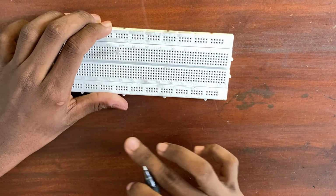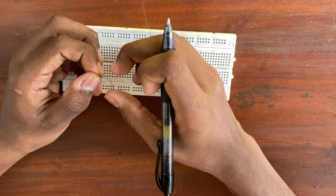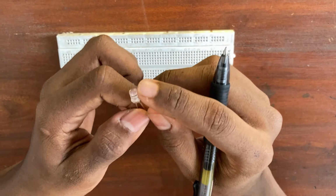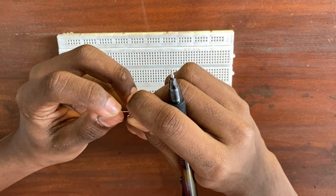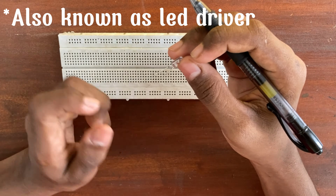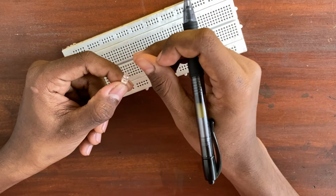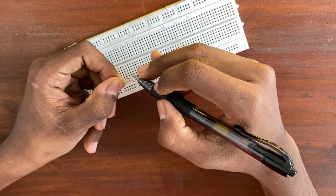This is an LED. It emits light when we give power to it, and when driving an LED, you have to use a resistor or a current limited supply. We generally use a resistor, but when it comes to driving high power LEDs, you will need to use a current limited supply. You can tell the negative and positive pins apart by the pins. The longer pin is the positive, and the shorter pin is the negative. We also call them anode and cathode.